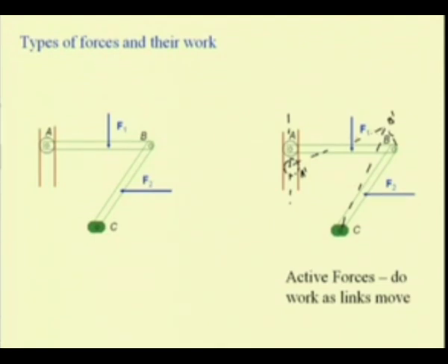We have to consider the work done by these forces, which we define as active forces, because these forces do work when a displacement consistent with the constraint takes place in the system of connected rigid bodies. Because neither do we see that the displacement is perpendicular to these forces, nor do we see that the displacement is 0. That means there is some displacement